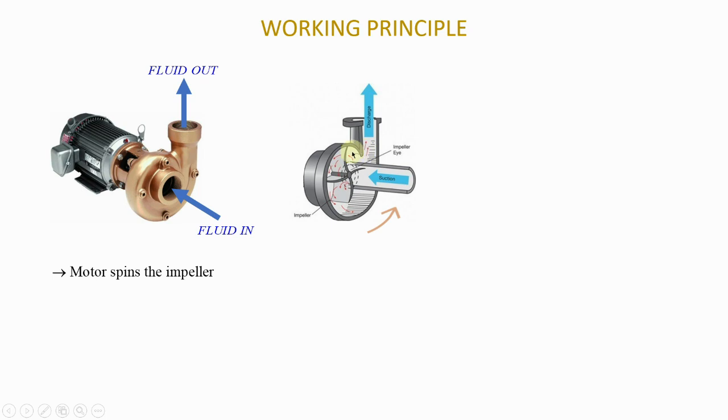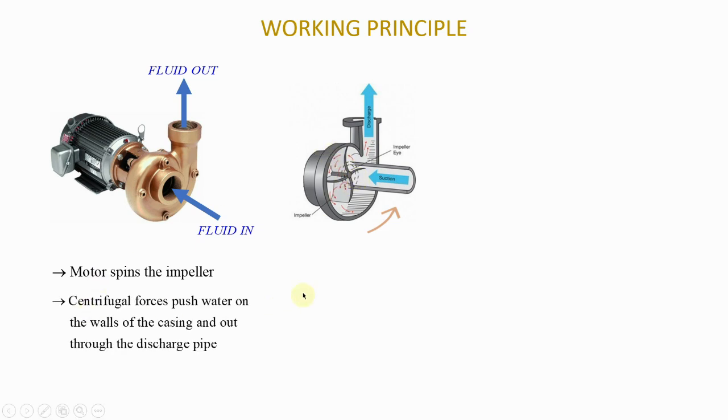As it does that, because the water is spinning, what will happen is that centrifugal forces will act on the water. Okay, and these centrifugal forces will cause the water to move away from the impeller's eye, or from the center of the impeller, and so the water will come and pretty much stick to the walls of this centrifugal pump. Okay, and the inside there will have a vacuum that will form.